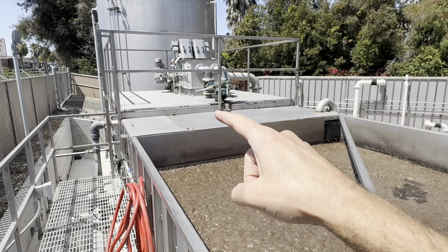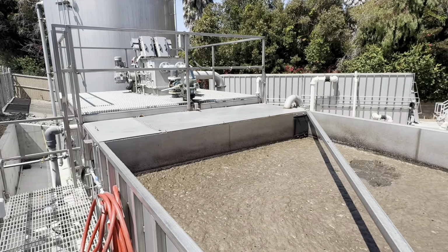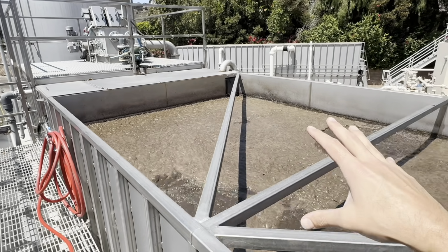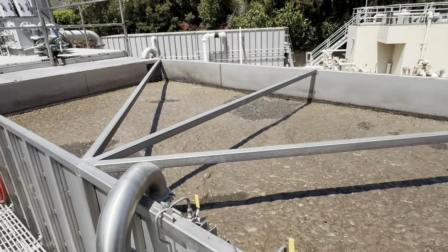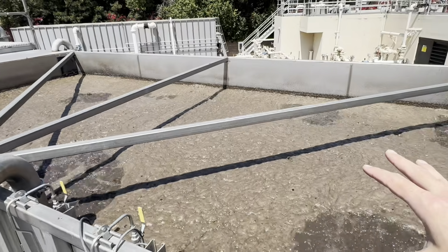Okay, so what you're seeing right over there is our anoxic zone. I'm not gonna get into that today because this is just an introduction to activated sludge. I really want to focus on aeration here. And what you're seeing with this foaming is, you shouldn't see this level of foaming in a conventional activated sludge plant where you're just doing BOD or TSS.